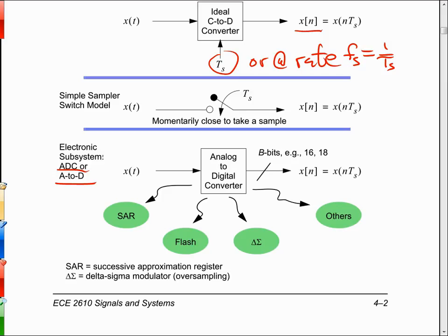Flash is a type of memory, but in the A to D converter business, what flash means is that you can have a comparator for every bit in the conversion process, or every quantization level. So if you were doing a 10-bit converter, there's 2 to the 10th quantization levels. So that's 1024 comparators that are needed so that as soon as the sample hits the front of the converter, you hit it with a clock and you say, what is this analog sample convert to in bits?